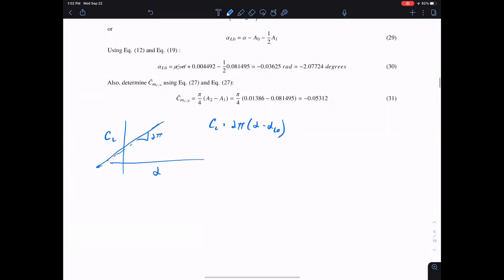So every one of these airfoils that we ever plot from thin airfoil theory is going to have a lift relationship with angle of attack that looks like this. What does that mean? Well, on this airfoil, if I increase the angle of attack, here's V infinity, and my lift, I'm just going to draw it at the quarter chord. Again, we could draw that anywhere, but my lift that's perpendicular here is going to grow linearly with the angle of attack. If I go from, let's say, 0 degrees angle of attack up to 1 degree, I'm going to have a linear change in my lift. My lift is going to increase by exactly 2 pi multiplied by the 1 degree. I'd have to change that to radians, because this is in radians. So 2 pi times radians. That's how much my lift is going to grow. If I increase angle of attack, my lift is going to go up. If I decrease my angle of attack, it's going to go down, right? So that comes right out of thin airfoil theory.